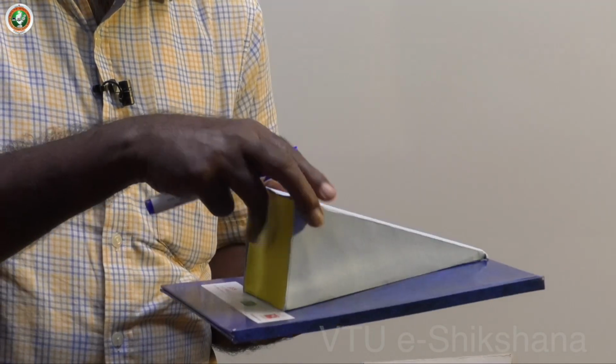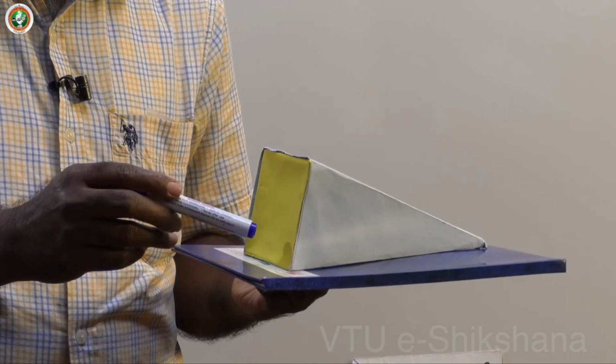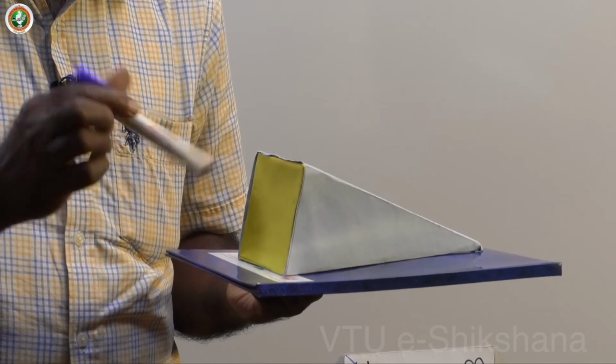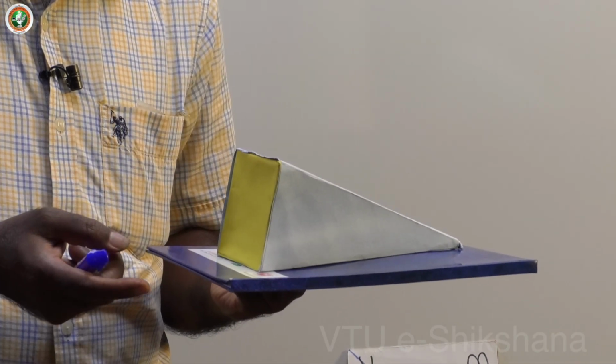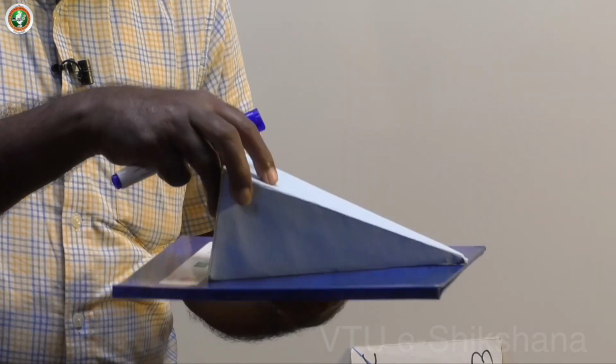Now, base edge on HP means this one. It need not be like this, it can be like this also. The triangular face, the slant face: one of the base sides is the base edge only. So, that base edge is inclined at some degree to VP. This is true length and true inclination. First position, second position, third position.